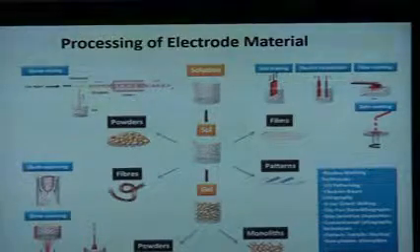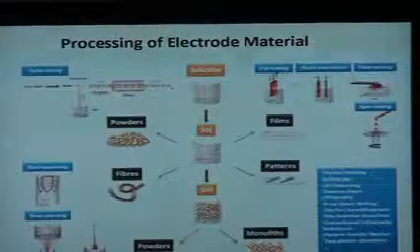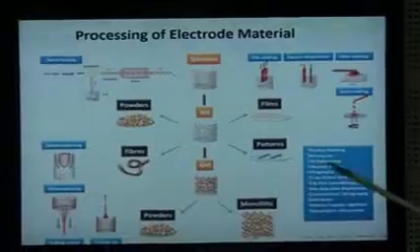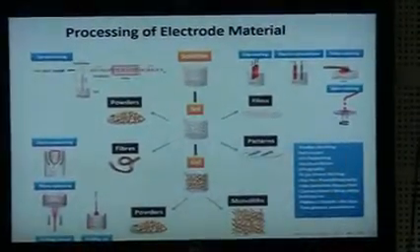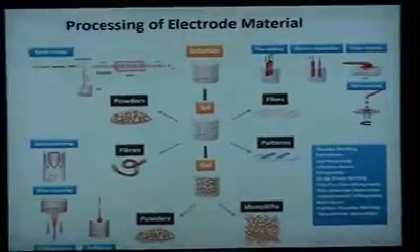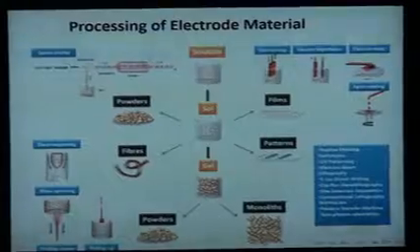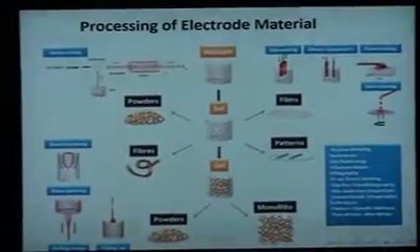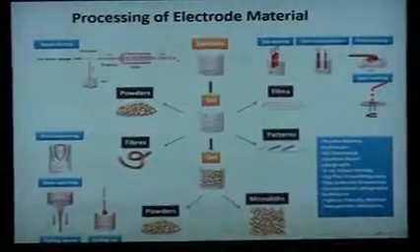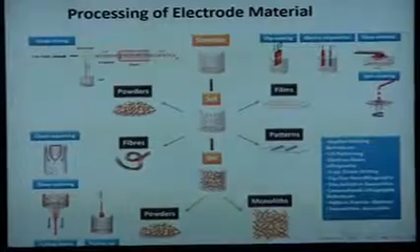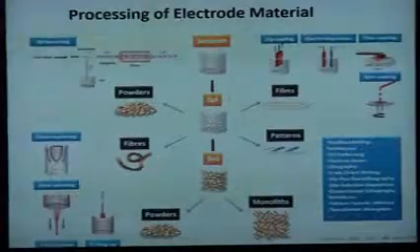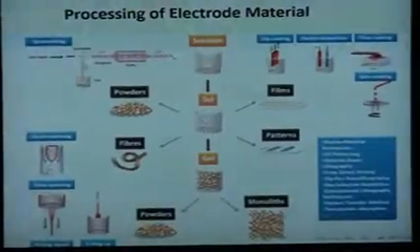So from synthesis to processing of material, what are the different techniques which one needs to adopt? You have particles in the form of a solution. Now you want to prepare a film, right? It can be done by different techniques like spray coating, solution dip coating, rod coating, or slot die coating. There are a number of techniques like this. So these are the commonly used methods for putting the material together when you have it in the form of a powder or solution, right?